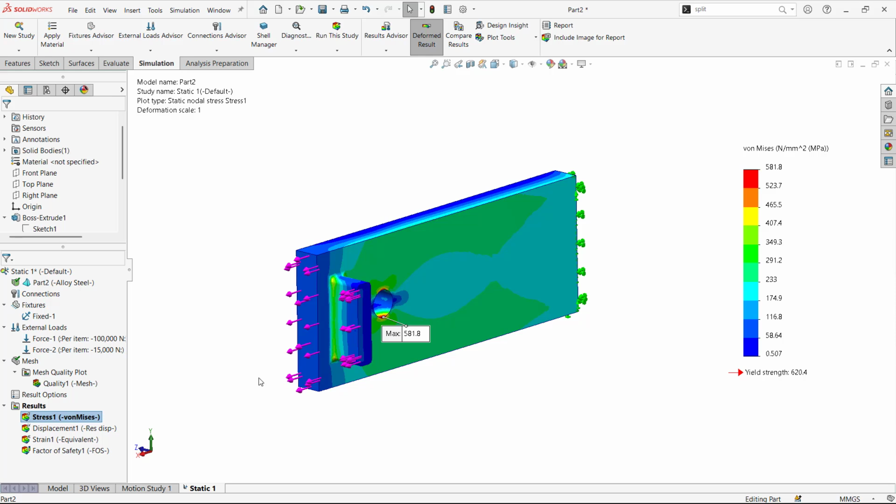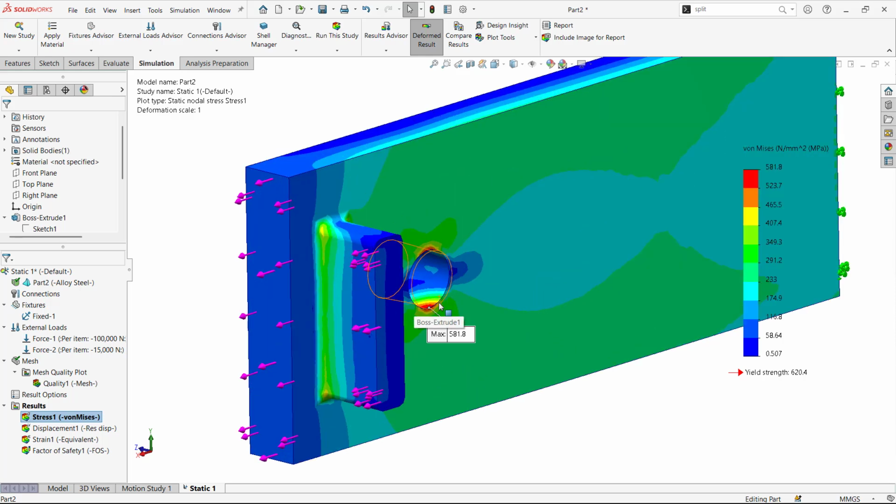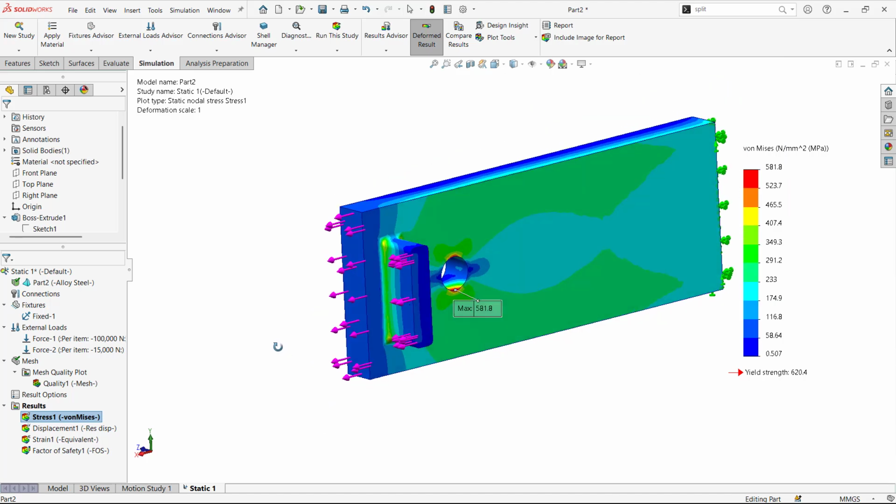You can even suggest to counterparts or your project owner that this is failing and these are the possible changes we could apply, and try to make sure this model is going to work. In short, if you want to reduce this stress hotspot, what is the best possible solution? I would recommend having a fillet here, right? But again, there might be some disadvantages with respect to machining. The manufacturing cost might increase, but you can propose a solution to the counterparts. If they are okay with that, they will proceed, or else they will tell you to remove the complete hole, not necessary. Or else you can even do the topology optimization on this one.